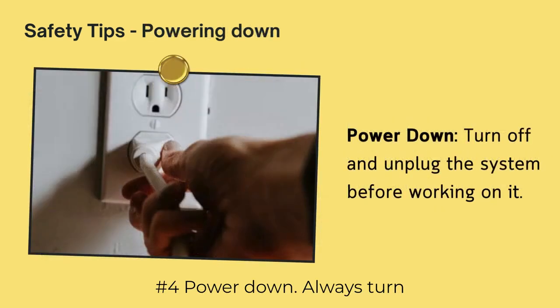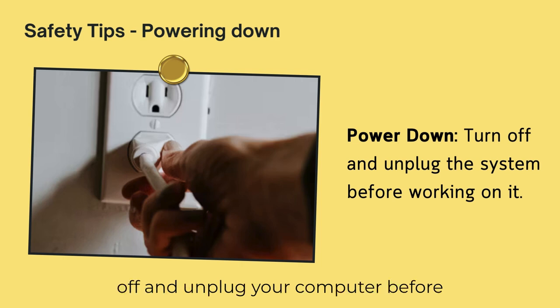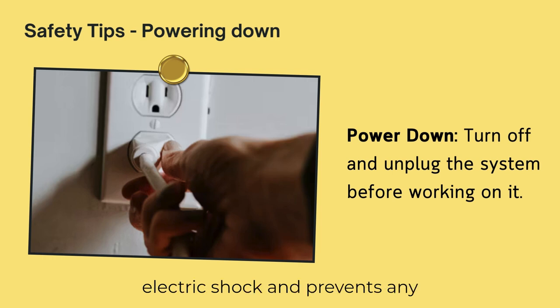Number 4. Power down. Always turn off and unplug your computer before working on it. This minimizes the risk of electric shock and prevents any accidental damage to components.